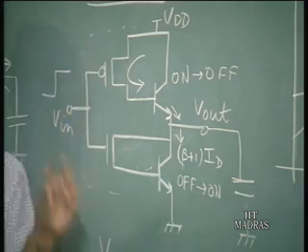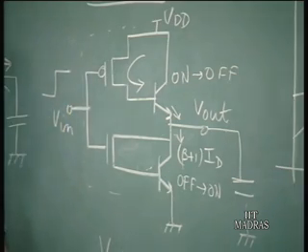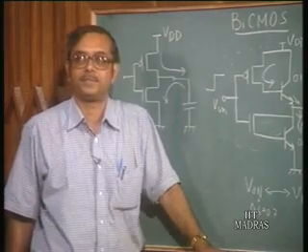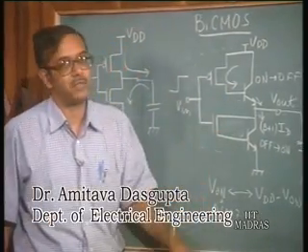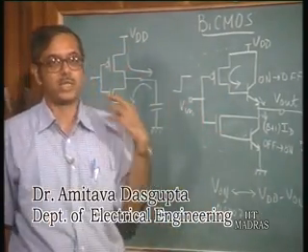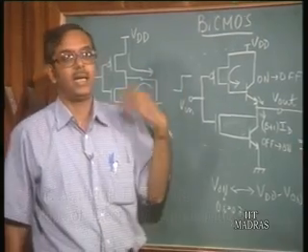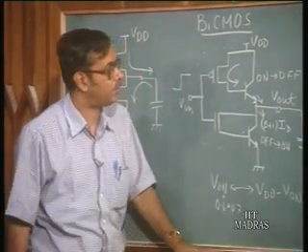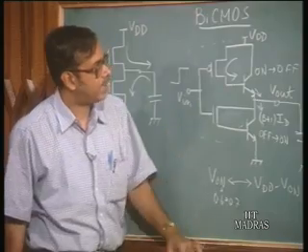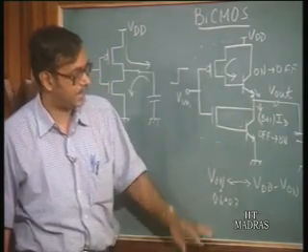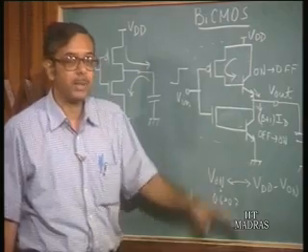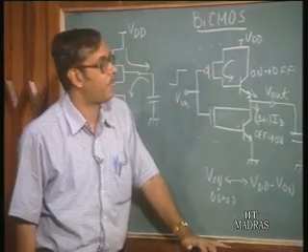You see that there is no real mechanism in this circuit for a reverse base current to flow for the bipolar transistor. We have always stressed, when we discussed bipolar logic families, that in order to switch off the transistor fast, we must have a reverse base current flowing, which draws out the base charge and switches off the bipolar transistor fast. So, that is one drawback in this circuit in its present form, because there is no mechanism to remove the base charge.